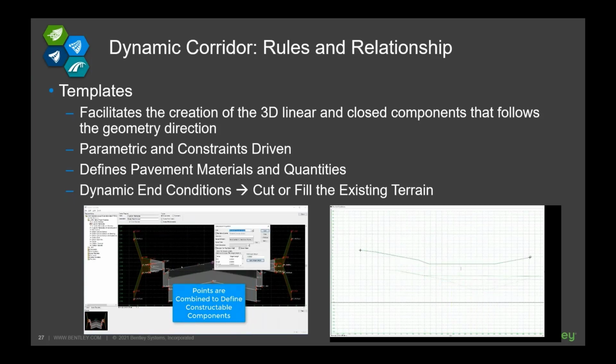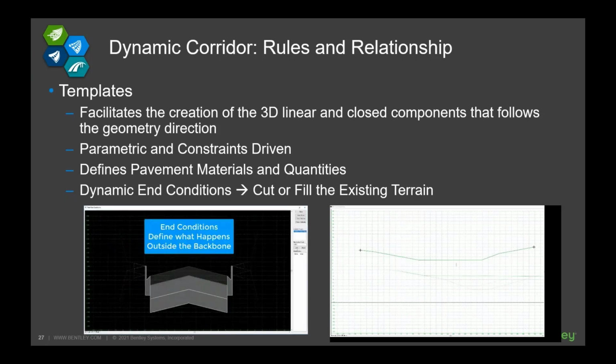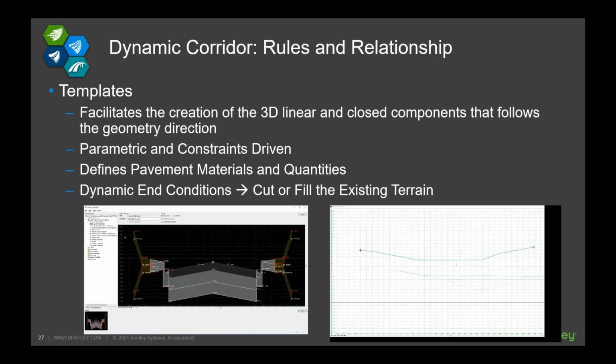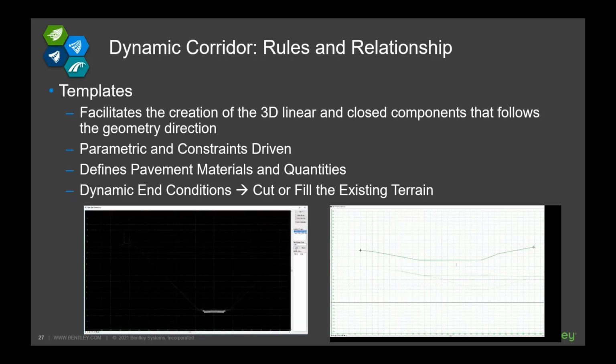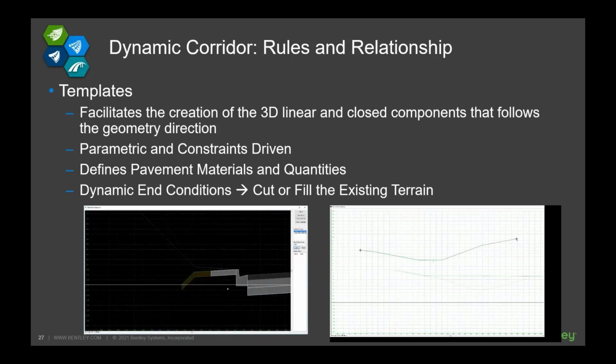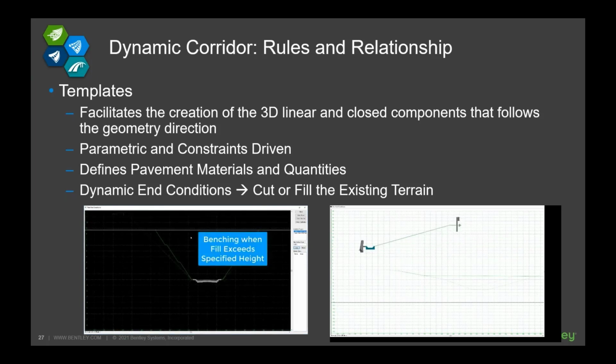That's it. And also, DWG can be readily opened inside any MicroStation-based software, which includes OpenRoads. But of course, it will stay as CAD, so probably you can just use that as a reference. The civil information there is not going to be intact. So you have to use the LandXML to facilitate the civil exchange of data between the two software.